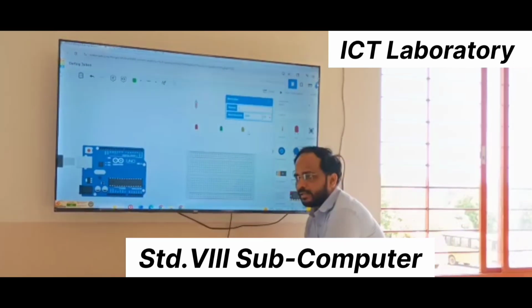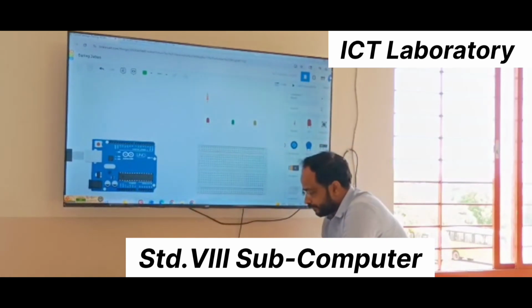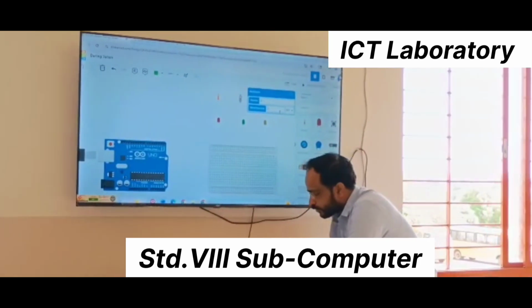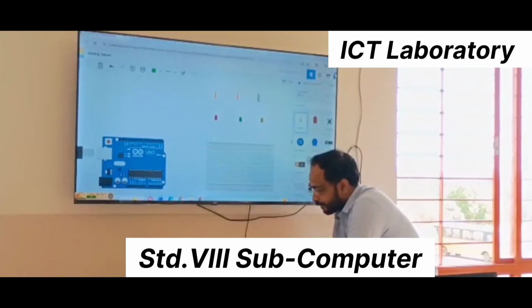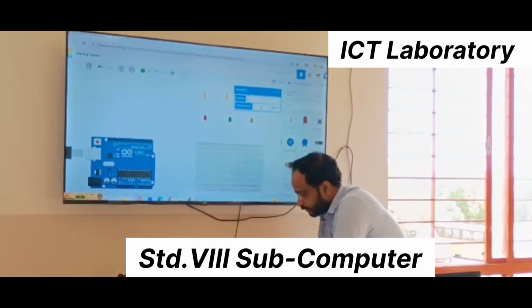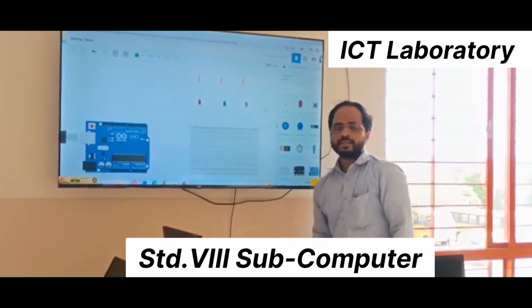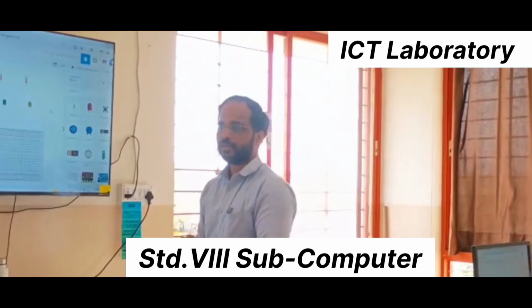Almost done? Similarly, you have to take 3 resistors here. This is the second one. Here also you can change the resistance to 220 ohm. Third one. Okay, now next step, now we have to do the connections.